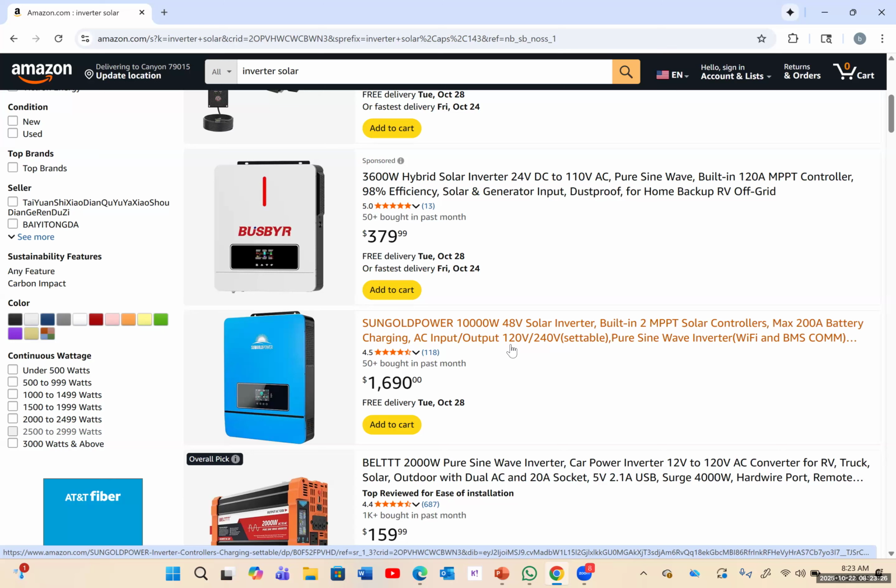Most of them are capable of two-way power delivery, meaning you have the inverter that does the control system to be connected to grid. So some of them are off-grid and some of them are grid-tied inverters. When you want to buy them, if you want to build a solar system for a cabin, which you don't have any connection to a transmission line, you're going to go for the off-grid one.